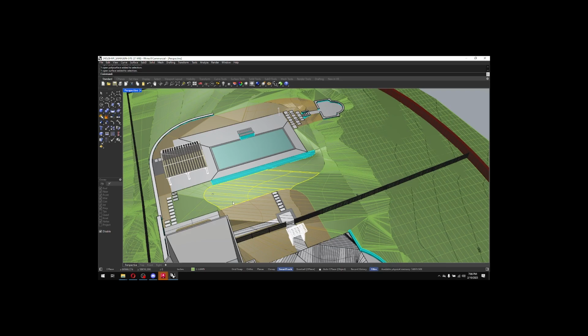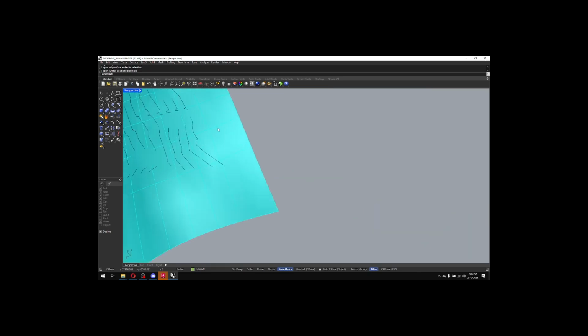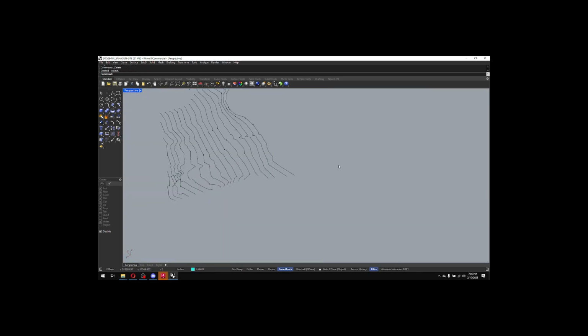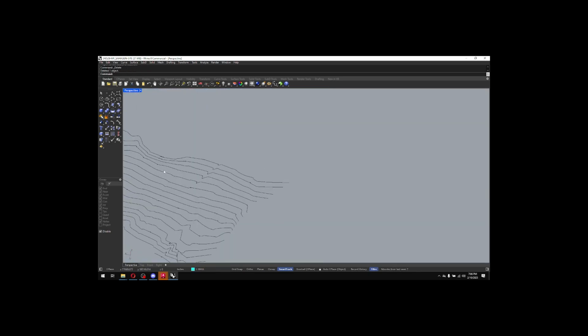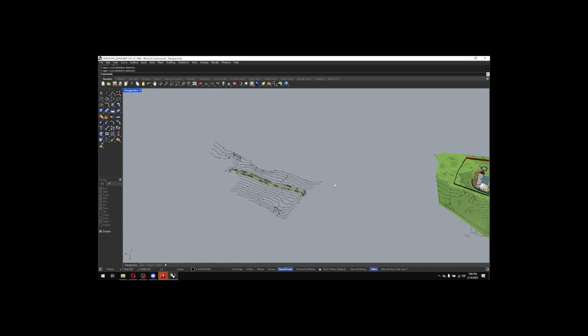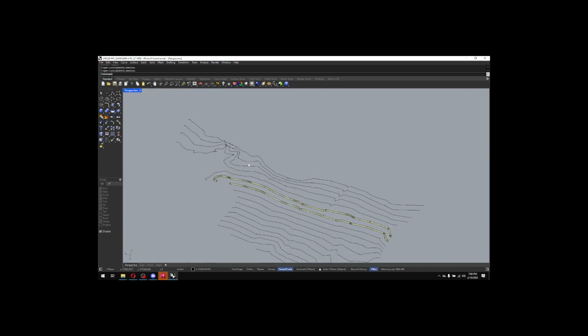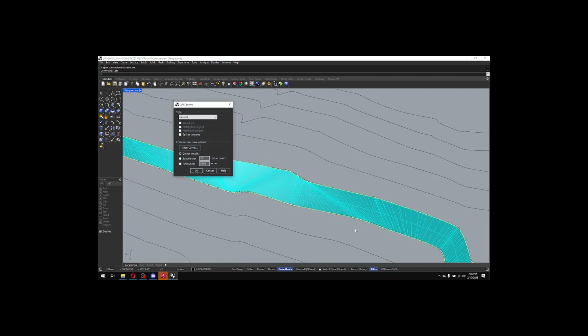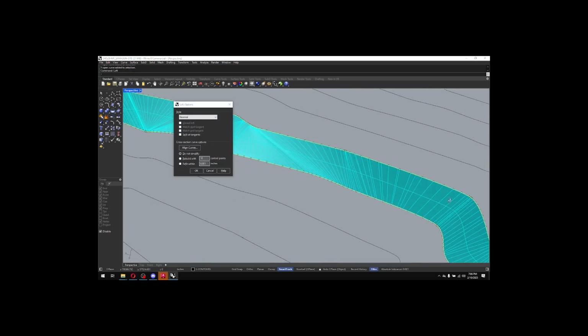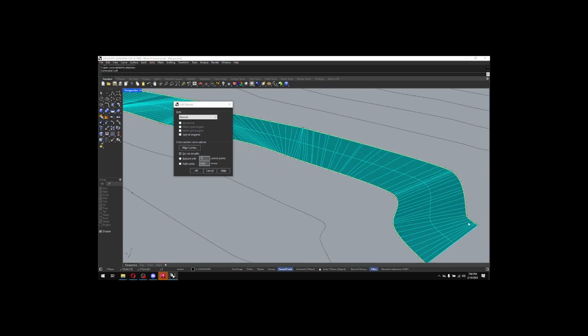You might have to break the contour off a little bit, because if I try to loft, here, let's delete this. This will be the last thing we do because we need to wrap up. If I try to just come right in here and loft these two lines together, I'm going to get a really funky shape. So you can see what it's doing is it's breaking down that curve into points and then trying to associate points in between the two curves.